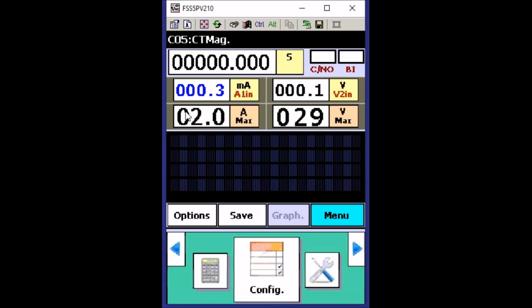If there wasn't a limit in this parameter here, this short circuit inside the transformer could have resulted in some smoke or something similar, okay, because this transformer was damaged in the secondary. This had a problem with the isolation, so it had a short circuit, but thankfully this function has a current limitation here. So normally you will get very low current in secondary, so just 1 or 2 amperes maximum would be okay. In this case I will set it to 1 ampere.